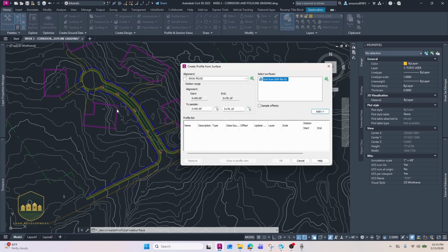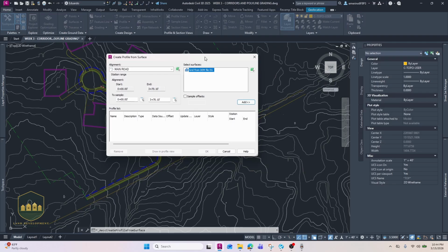Right here you have about 4 feet of elevation difference running through the house. Really doesn't make any sense. You want the house to be flat. So there's definitely plenty to manipulate that we need to change. I mean, look at this house over here that has 1, 2, 3, 4, 5, 6 foot elevation difference. And we will show you how to grade that later on.